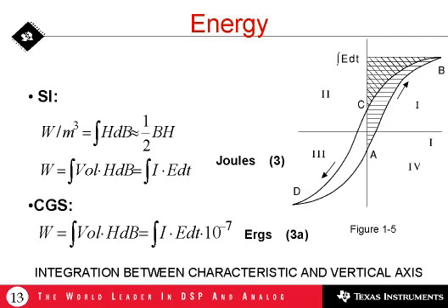In order to store significant energy, it's necessary to add a gap in series with this core, and that will linearize the characteristic and skew it out to the right, and we will now get a much increased area between the characteristic and the vertical axis, which represents stored energy. And the amount of that which is gone in the hysteresis loss is proportionately reduced. And so our inductor now is becoming more effective.